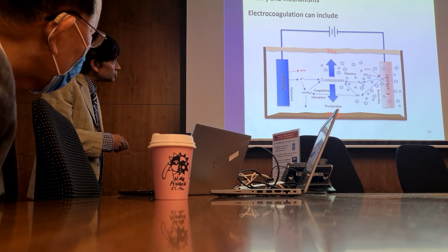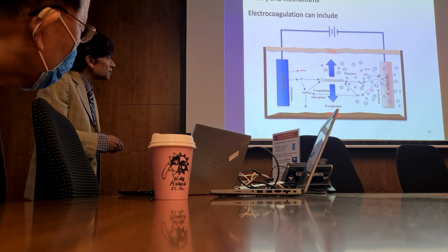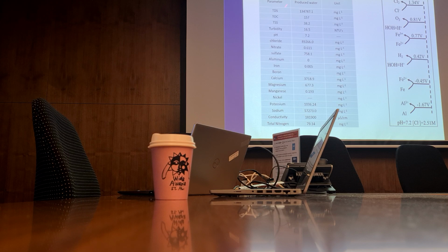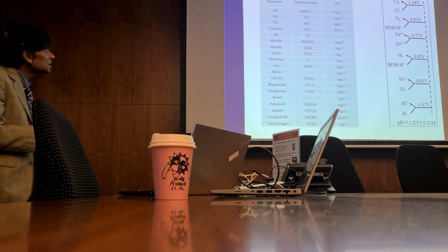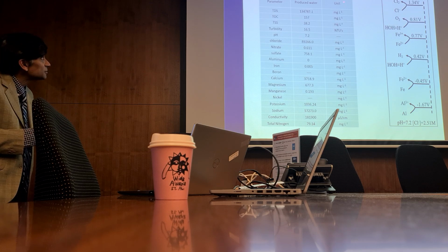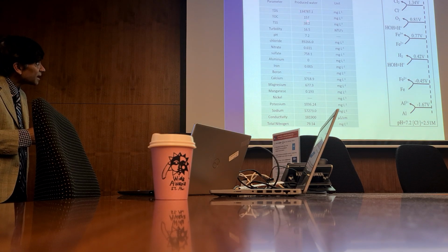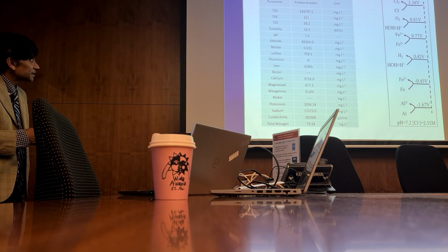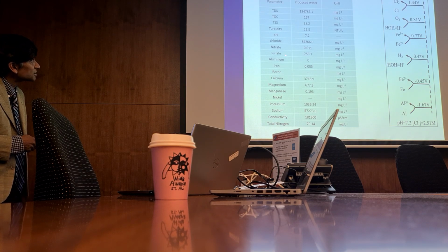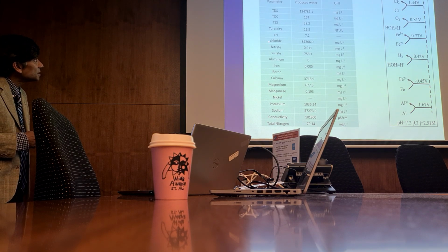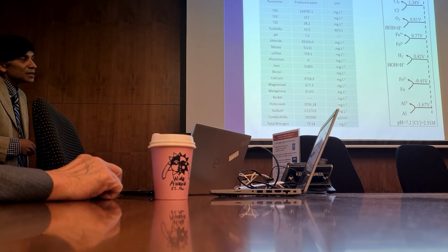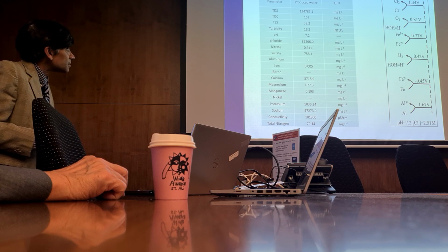At the cathode, you will get production of hydrogen if you're reducing water. However, that's in DI water. It's not quite as simple as this. So this is an example of our produced water. You can see the TDS is very, very high, right? 134,000, much higher than seawater. Total organic carbon is high, and that's what's causing fouling of the membrane distillation membrane. But you can see in this case, the major ions that are present, and actually most of it happens to be sodium and chloride. But it could be some other things as well, calcium and so forth.